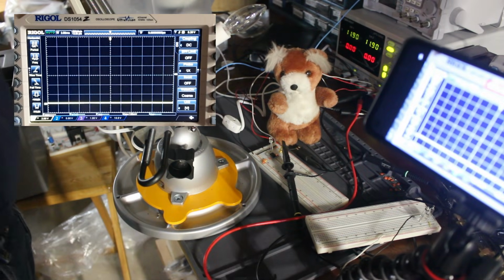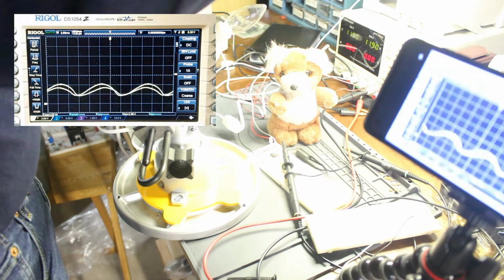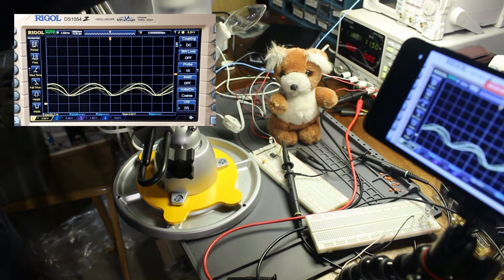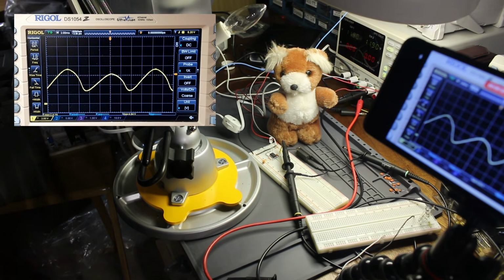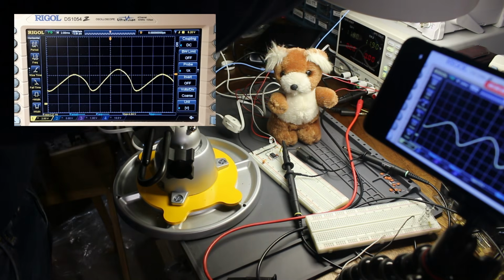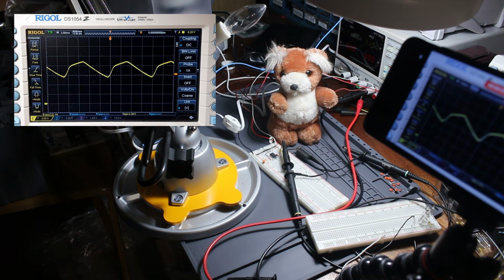Now let me try a few light sources. The first one is an old-school fluorescent ring light, not a newfangled LED one. You can see a pretty extreme variation of the light intensity with every half cycle of the power line. The persistence of the phosphor keeps some light present during the zero crossings. A modern LED lamp shows a similar 120 Hz variation, but less extreme, and with a peculiar waveform. I might have to take one apart at some point to see what the power supply looks like.